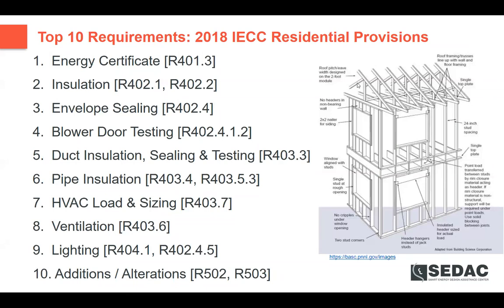The code official is likely to be concerned if the builder who built the building would want to do the blower door test, because of a real close conflict of interest. An architect or engineer is likely acceptable, but again, it's determined by the code official whether they would be an independent source.